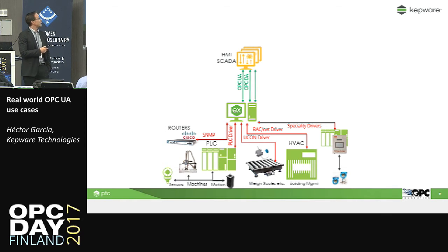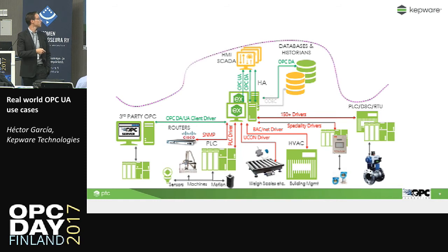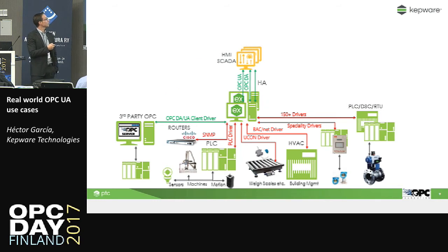And very important is that sometimes some customers already have legacy OPC servers, and we can also connect and act as a kind of concentrator of the communications, so that the clients may only need to communicate with one single OPC server instead of creating many different connections.